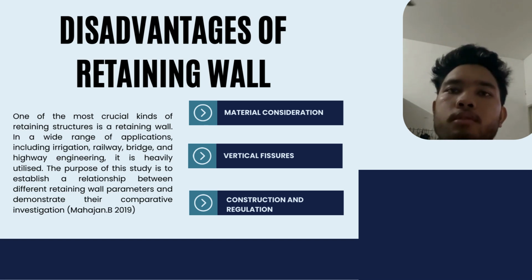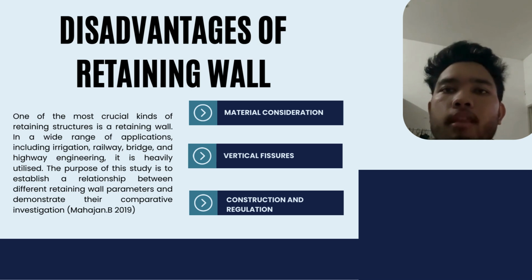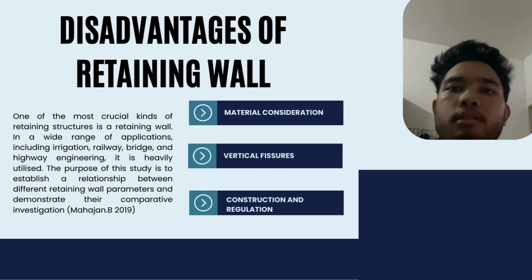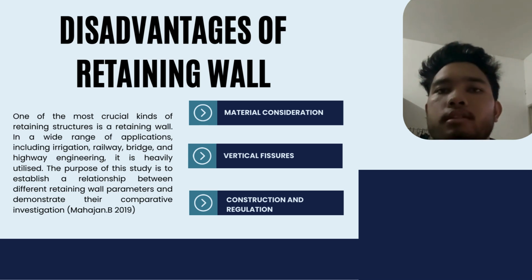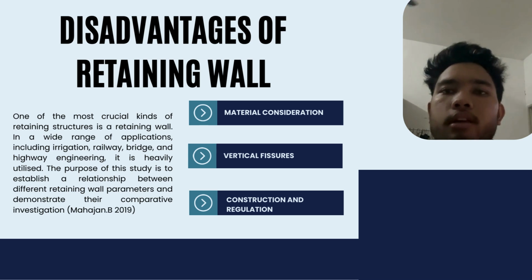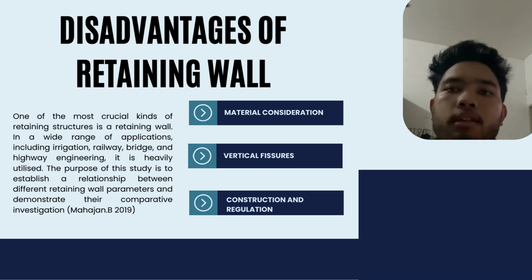Whenever you use wood for a retaining wall, your property may become the target of termites. The gravity retaining wall's weight is the only thing that can resist lateral earth pressure, because they need high gravity loads to offset the horizontal soil pressure. Gravity retaining walls are frequently very large. Bearing, sliding and overturning forces must all be taken into account when constructing a gravity retaining wall.